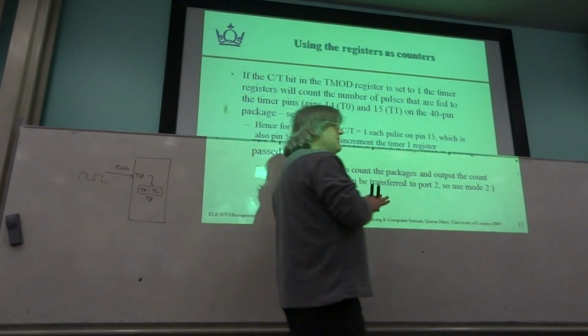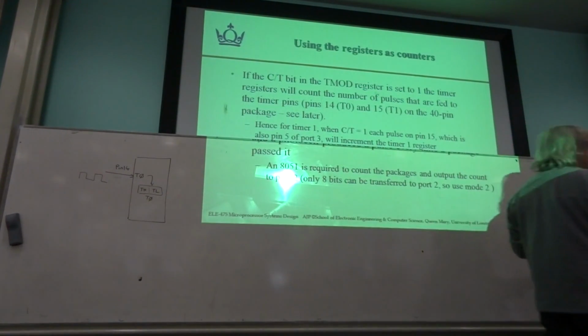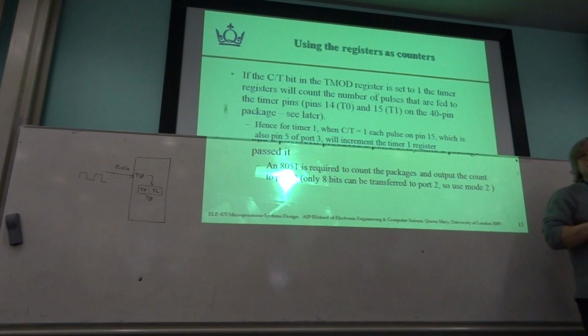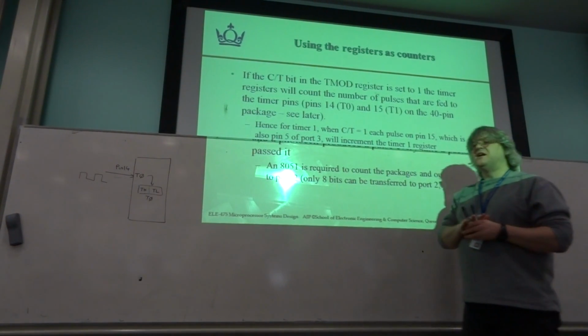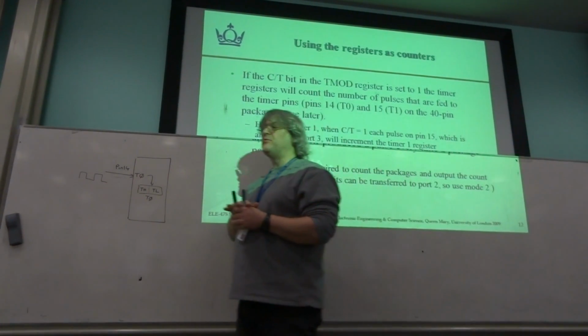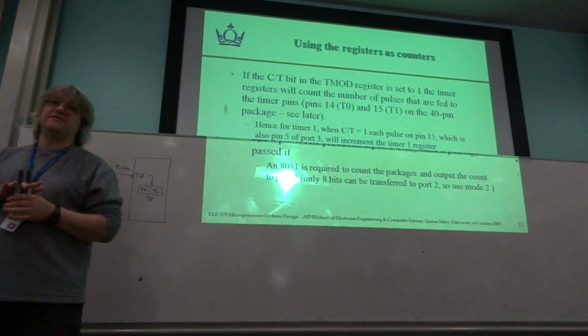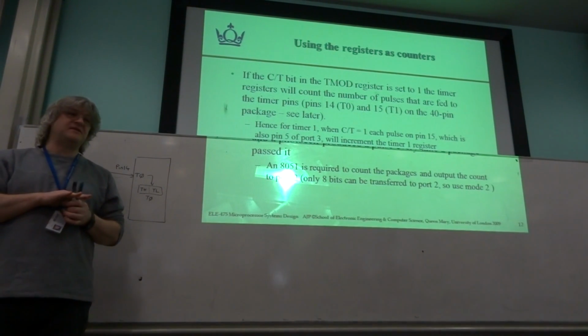If you're using the timers as I've described so far, where we're not making use of interrupts, when a timer overflow takes place, it is your job, the person that wrote the program, to make sure you clear the flag. It doesn't happen automatically.